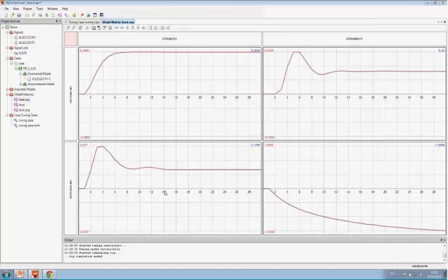Now this is the two interacting loops in the Nemo case. We have the total flow going to the plant. If the valve position increases, also the flow will increase. The valve position increases, then also the pressure will build up in front of the expander. Now if we increase the speed of the expander, the flow will go up and the pressure will go down. So these two loops are clearly interacting with each other.